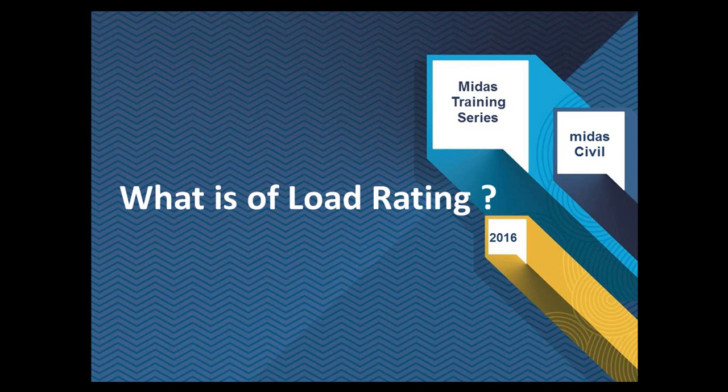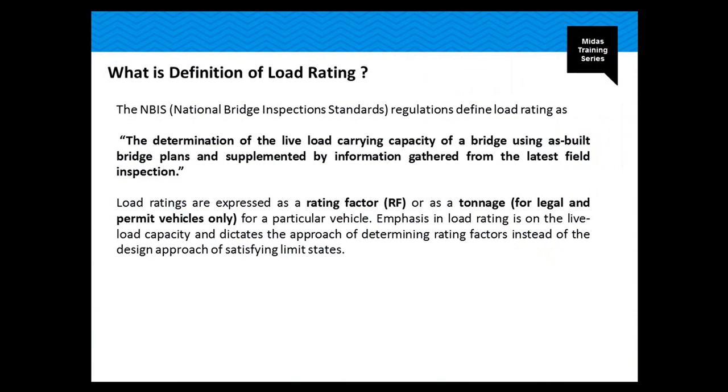Now, going into the topic that we're gonna go over today, what is the bridge load rating? The National Bridge Inspection Standards defines the load rating as the determination of the live load carrying capacity of a bridge using as-built bridge plans and supplemented by information gathered from the latest field inspection. It is basically the load carrying capacity of a bridge. It is expressed as a rating factor, which is RF, or as a tonnage, for legal and permit vehicles only.